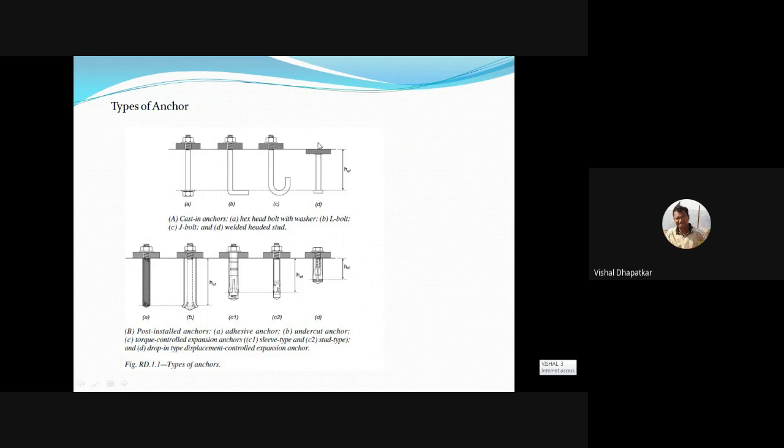And these studs are the bolt type where we need an embedded plate, right? Sometimes we provide an insert plate. You must have heard about insert plates. So that insert plate will be welded to these studs, and these studs will then be embedded in the concrete before the pouring. So these are the cast-in-situ anchor bolts.